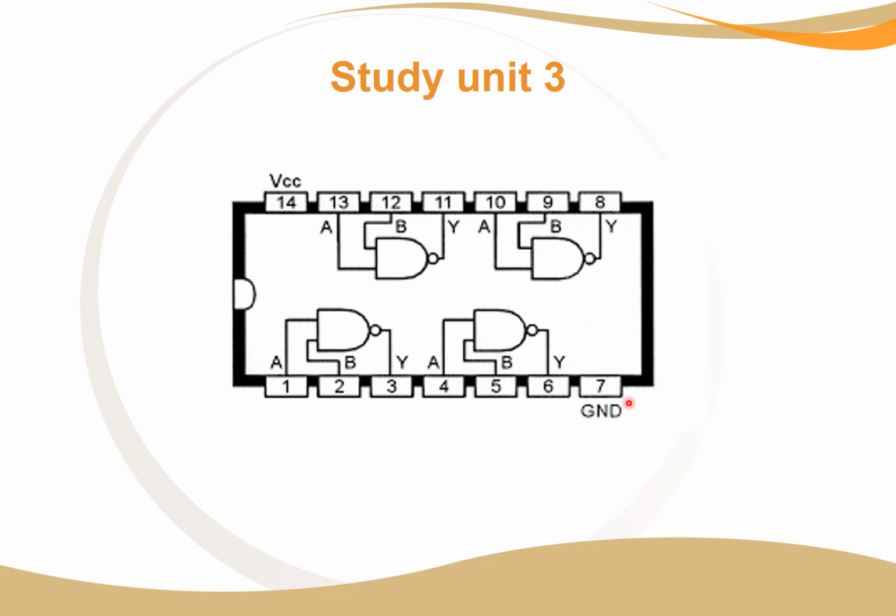Here we have to connect pin 7 to ground, and pin 14 we have to connect to positive voltage. Depending on what type of chips you use, but we're using TTL, so it will always be 5 volts. Otherwise, if you don't connect it to 5 volts here and ground there, your chip will not work.